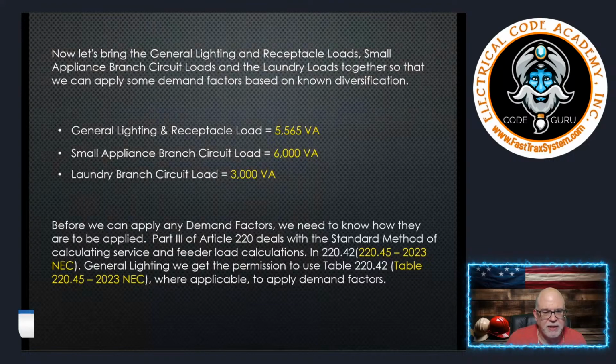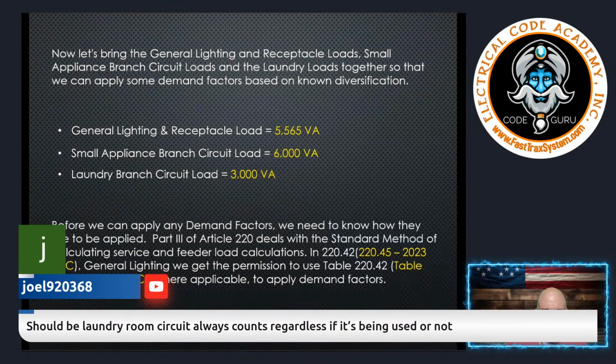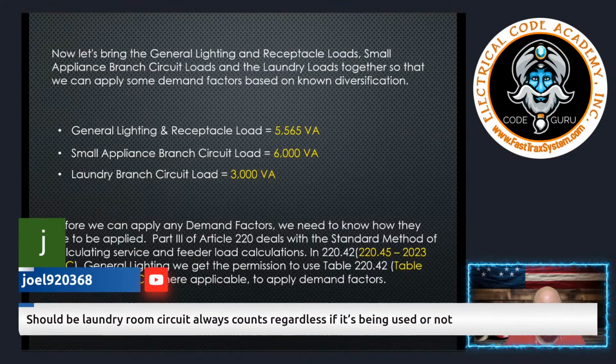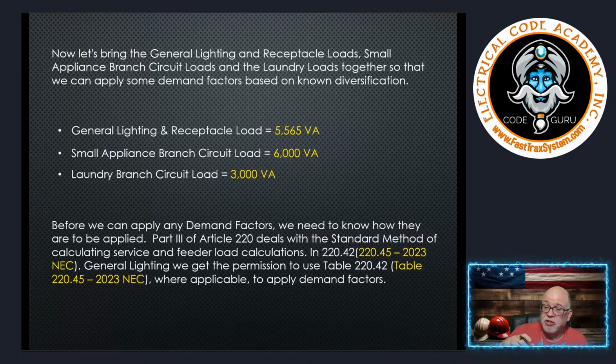Let's see here. Question we had from the chat: should the laundry room circuit always be counted regardless of whether it's being used or not? You have to have a laundry circuit, period. Unless you're dealing with a multifamily dwelling that has a laundry facility on site that is available to all of the tenants, it doesn't matter whether you use that laundry room or not. You have to have at least one 20 amp laundry circuit. Okay? Got to have at least one.